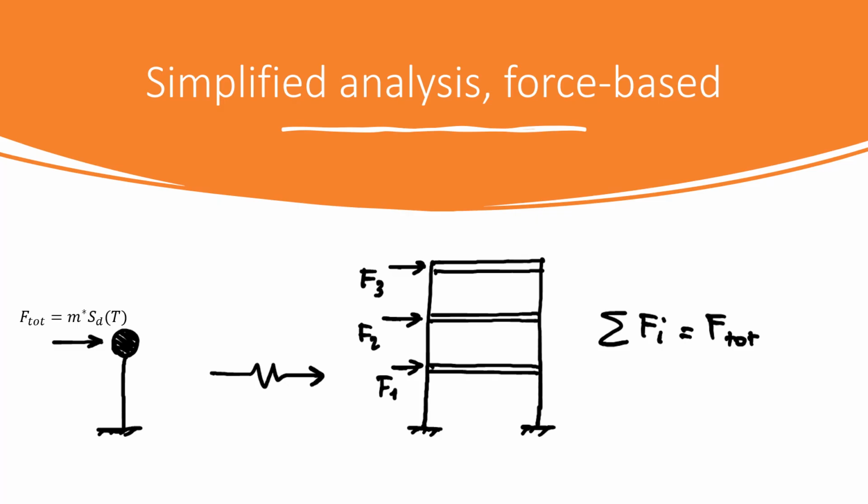Another characteristic of the linear methods is that in this simplified analysis, we normally use a force-based approach, which means that we use this method to compute internal forces, actions acting on members, on specific portions of the structure, and compare the acting force with the strength.